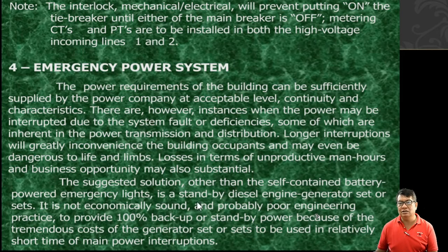The suggested solution, other than the self-contained battery-powered emergency lights, is standby diesel engine generator sets. It is not economically sound and probably poor engineering practice to provide 100% backup for standby power, because of the tremendous cost of generator sets relative to the short time of main power interruptions.